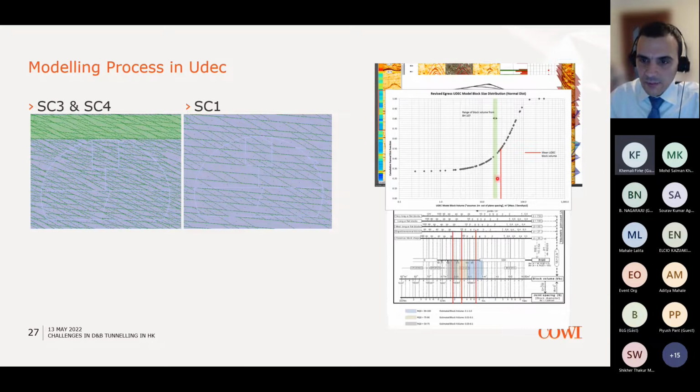So the 50% would give you here on the horizontal axis a typical block size of X. And we would then have to compare that against the size of the blocks that we would derive from the block size assessment from a particular borehole. And that's shown here indicatively by this hatched area. So if the two are close enough, it would mean that our calibration is sufficient, and then we would have high confidence that what we're trying to model accurately represents reality.